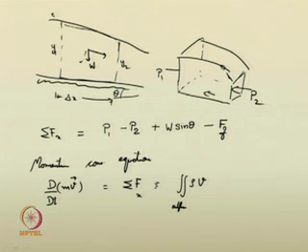In this control volume, the momentum flux coming out of this control volume along this surface is a positive quantity, whereas the momentum flux across this surface, perpendicular to this surface, will be a negative quantity, because the outward normal vector is in the opposite direction of the positive x. So, therefore, like that you can suggest now.